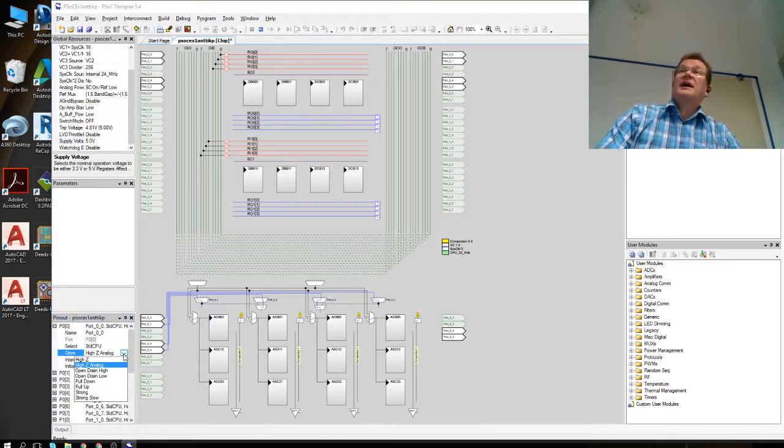Drive. Okay, that's a little bit different from processor to processor. Usually, with most processors you can turn the output drive to either strong, or pull up, or high Z. In PSoC, there's a little bit more selection. By default, this is defined as high Z analog, at least for port 0.